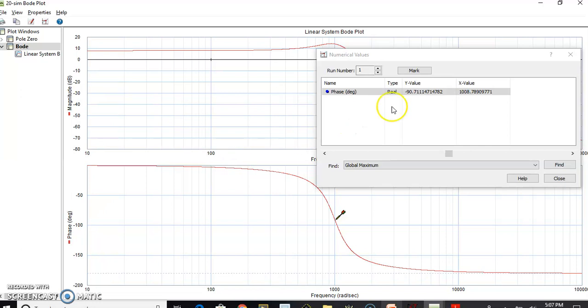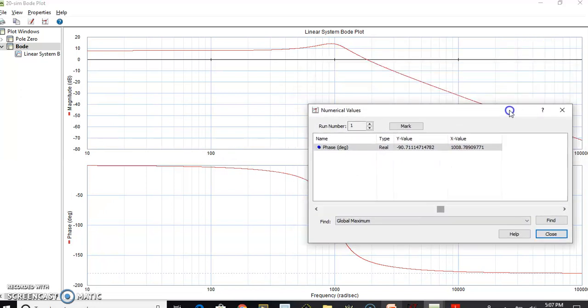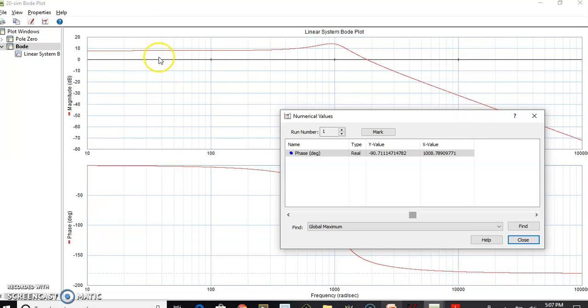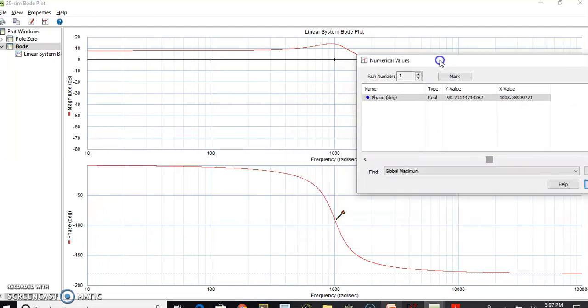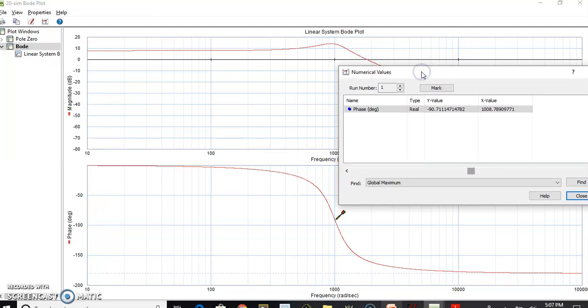You can see the poles have come closer to the imaginary axis, and let me see the Bode plot of this. We should have an overshoot response. You can see there's an overshoot response. The magnitude plot has got an overshoot here. This is flat here, and now you can see this is the overshoot. This overshoot response is due to a larger gain, more than 1.56. So this is how we can see the value of A, which is related to the quality factor. As the pole quality changes, we get an overshoot response. In the previous case, when the gain was equal to 1.56, we got a maximally flat response, and this is for a gain which is more than 1.56.